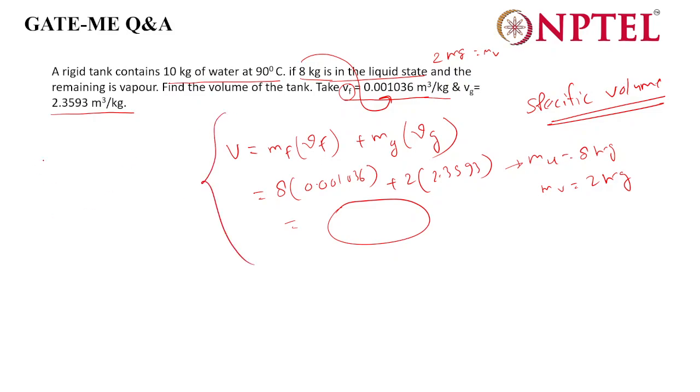So you are saying we will be considering it as wet vapor. So first you have to find the dryness fraction. What is the dryness fraction here? 0.2, sir. Correct? So V at 0.2, what formula have we written? V at x is equal to Vf plus x times Vg minus Vf. Correct? Yes, sir.